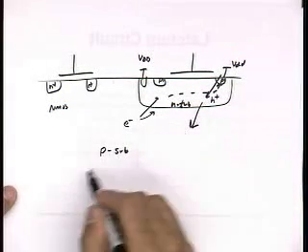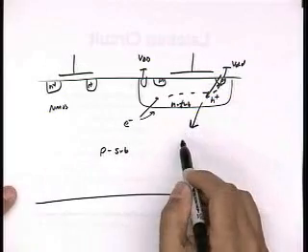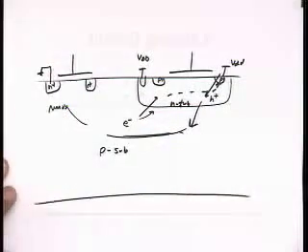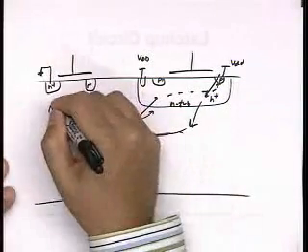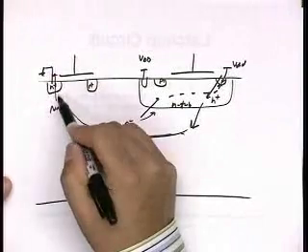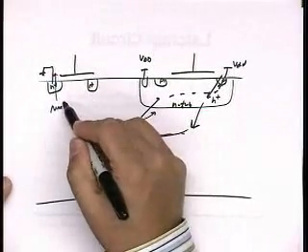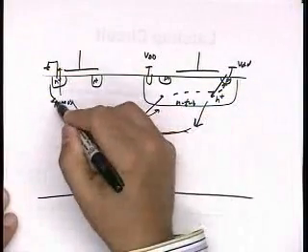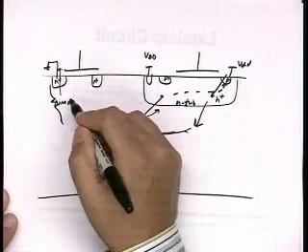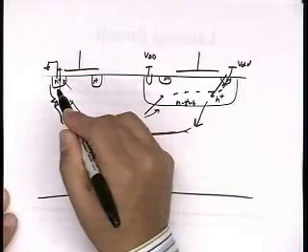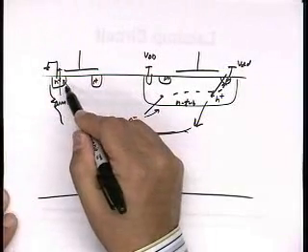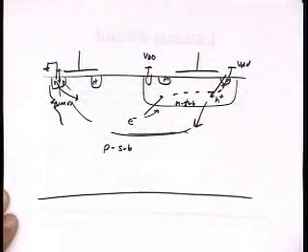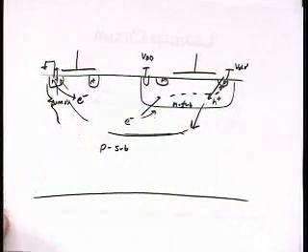Now when the hole is in the substrate, it's a majority carrier, so it can flow, and it might so happen to come across your little NMOS device, which is close by, and which is again a reverse bias junction, and it'll flow to ground, right? Now what happens? Again, this is a resistive material, so the fact that the hole crossed here and went to ground charges this point a little bit positive, which just a little bit forward biases this PN junction, right? Which means another electron gets injected, right? And I think from here you can see what happens.